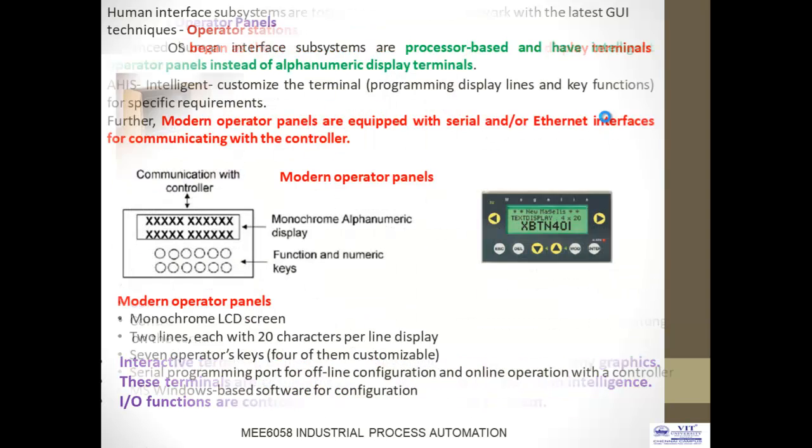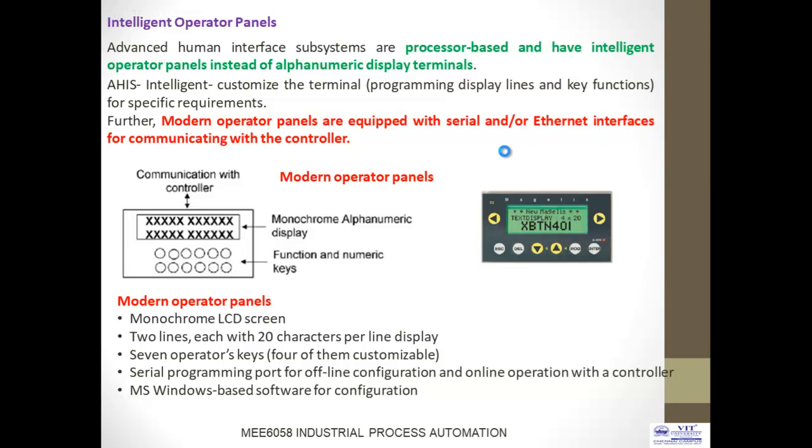But with a graphical user interface, you can drag the icon and put it in the operator panel, and if anything happens, it shows the alarm in the graphical icon. It says the problem is happening in turbine 1, turbine 2, turbine 3, turbine 4. You can troubleshoot the problem as quickly as possible compared to conventional operator panels.